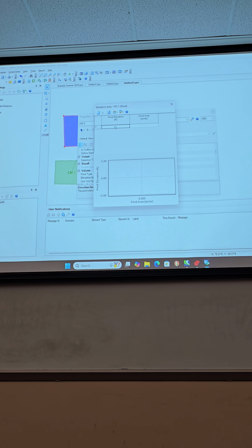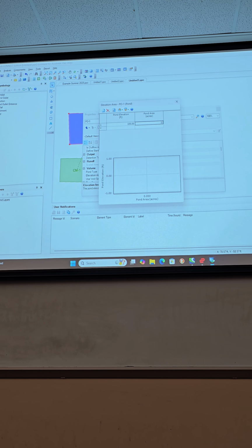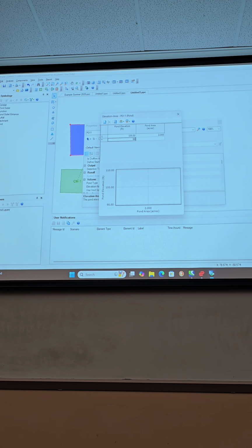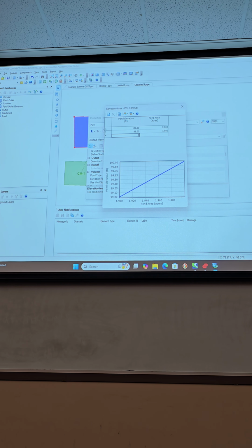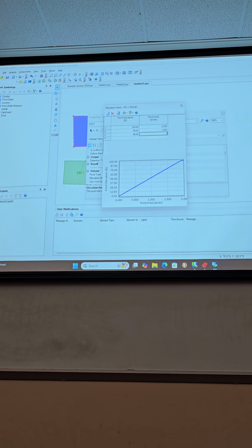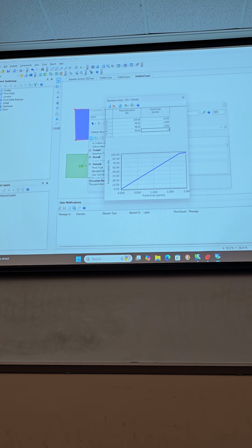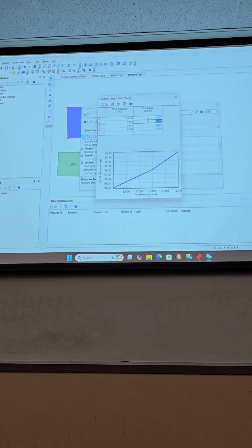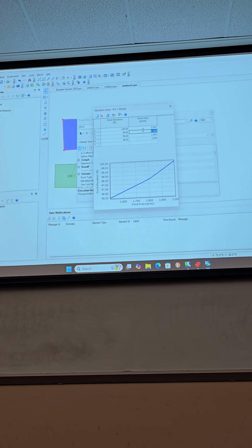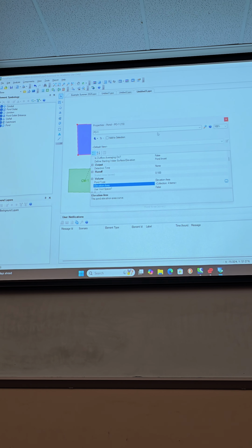So here I can put in elevation 100 and my area, let's say it's 2 acres, then 99, 1.9 acres, then 98, right, you get the picture. So then, let's say we'll put in 96 and 1.5 acres. So that defines the area elevation information for the pond. That's how I'm going to generate my volume, okay? So I've got that defined, okay?